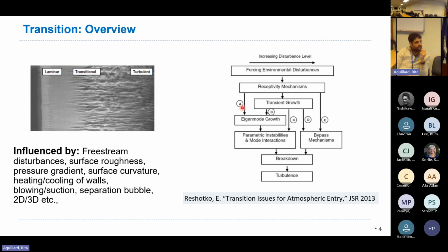So we're going to assume some linear assumptions and not talk about the nonlinear effects as much. And then essentially more to do with modal disturbances. So you have Tollmien-Schlichting waves under that, Görtler vortices, those kinds of things. And typically pathway A is more relevant to subsonic flows with mild disturbances.